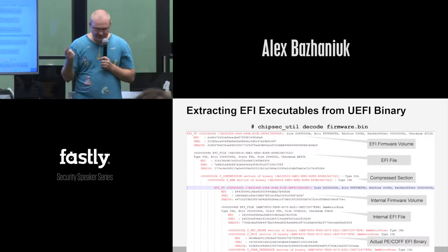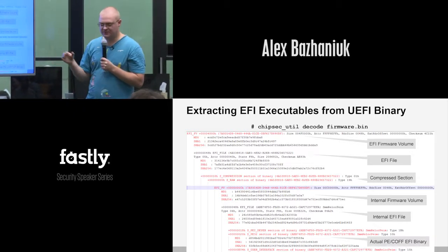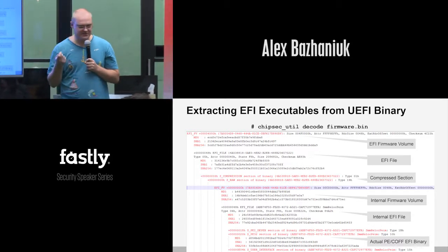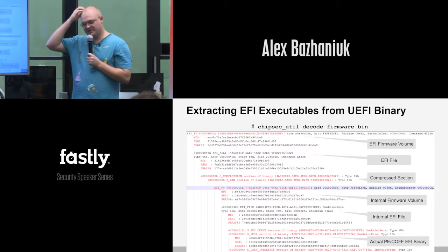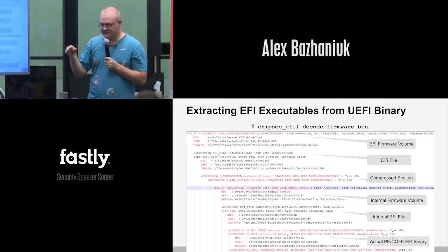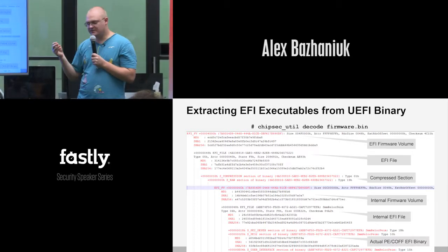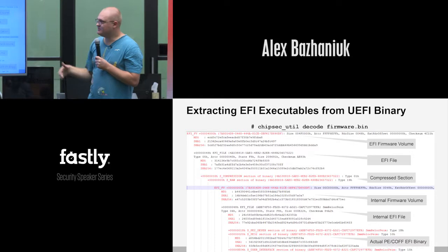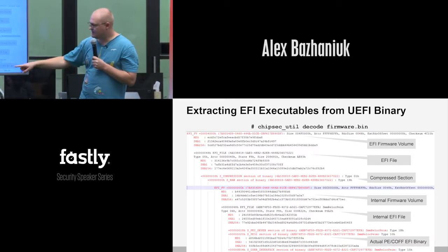So I was mentioning a couple of times already that you're working with the firmware, comparing the hashes, but what are these hashes from? The firmware in x86 systems, UEFI-based firmware, has a complicated structure. It's sort of a small file system in the SPI chip, which has volumes, sections, and then compressed binaries and so on. So here is the example of the hierarchy. We are looking for the last one.